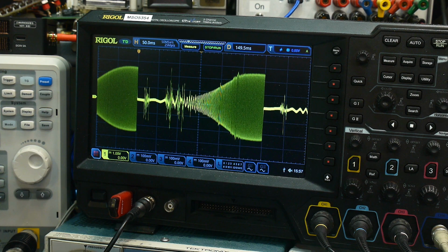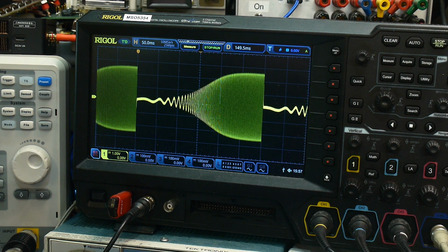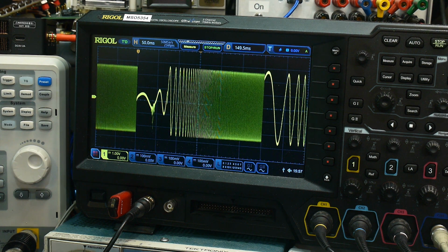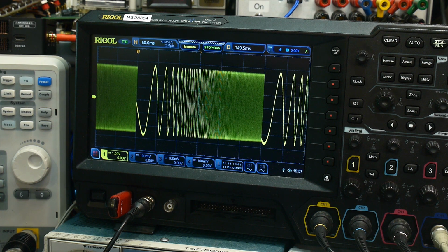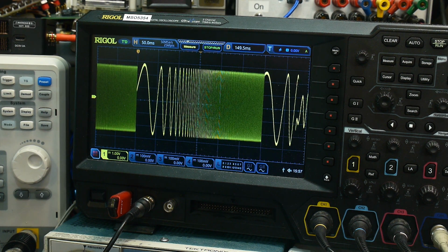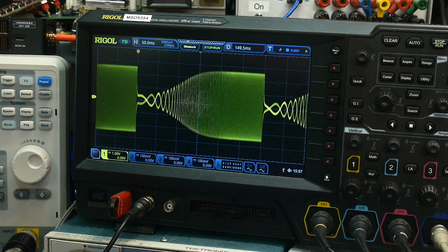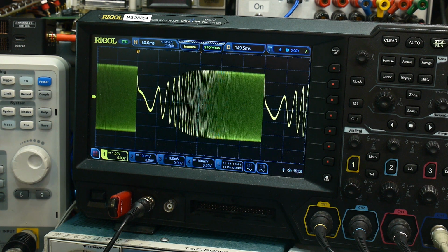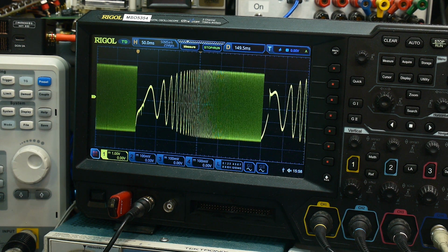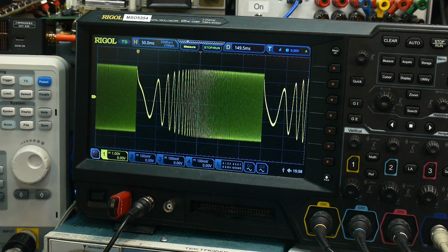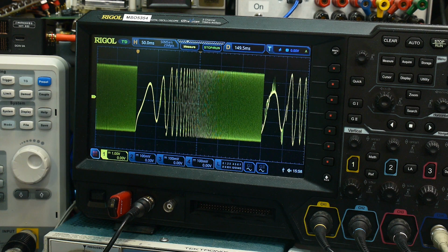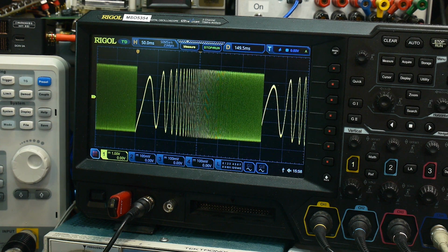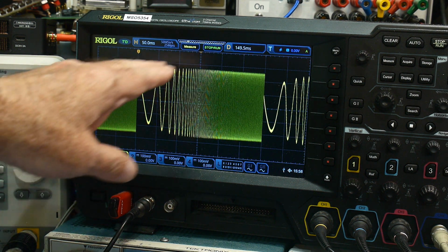Now I'm going to change it a bit. I'm going to go to 220 ohms, 560 ohms, that's 15K. That's not doing anything. 1K. Okay, 1K is doing a little bit. Oh, wait a minute. That's 1.5K. 2.2K. That 1.5K is not working on my thing here. 4.7K. All right. 8.2K. And we get down to 10K. It's going to be almost nothing. A little bit of roll off here.